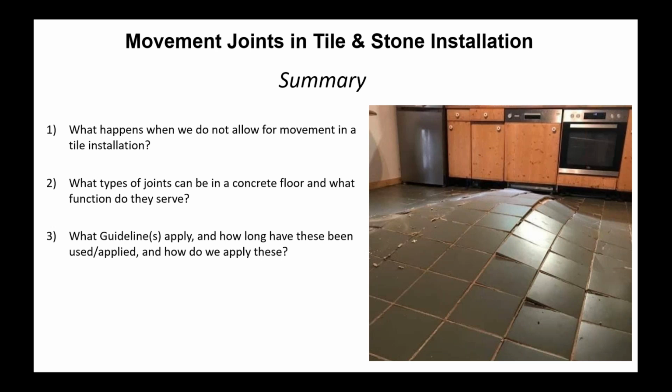So we stopped in the Pueblo Mall, and what the guys were doing is they were lifting out a 30 by 30 area, removing all the tile, reinstalling it, and putting in proper movement joints. In other words, all the tile had failed. They knew it was hollow and it failed, but the reason it had failed is because of movement, and they were putting it back in, and then of course putting sealant in some of the joints.